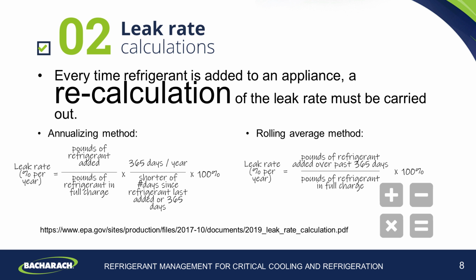Sure. It's just much clearer and simpler than the annualizing method, and so we recommend using that. The EPA simply state that the same method must be used for all appliances across your record keeping. So whichever one you do choose, just make sure you're consistent. And also the leak rate must be calculated every time refrigerant is added or removed from the appliance.